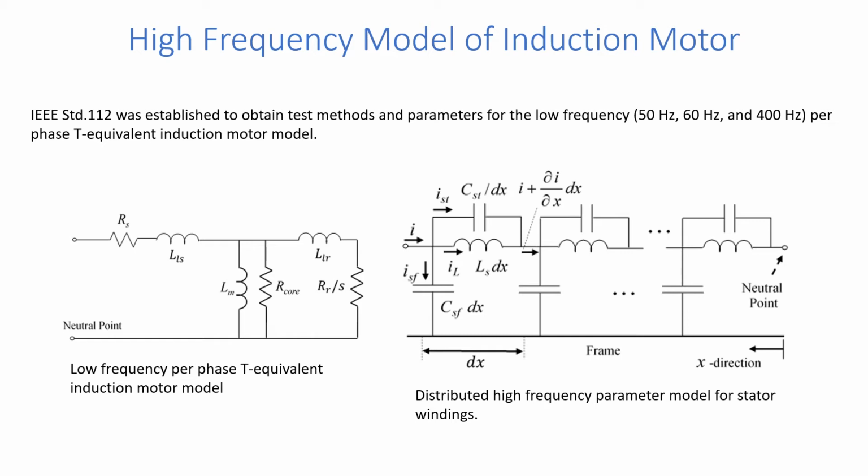The same study as we did for a simple magnetic circuit or inductor can be done for permanent magnet and induction motors. Let's focus on the induction motor. On the left side, you can see the IEEE Standard 112 model, where the parameters can be obtained from finite elements at the design stage, or using locked rotor and no-load tests when the motor is prototyped.